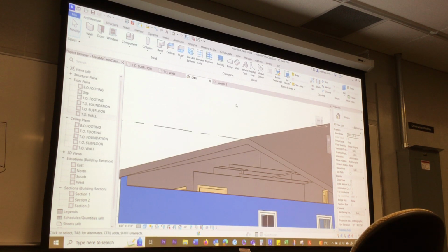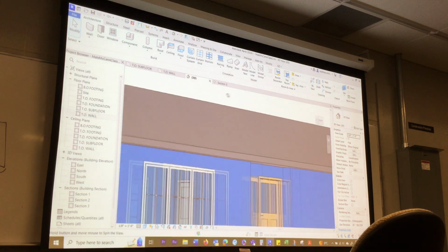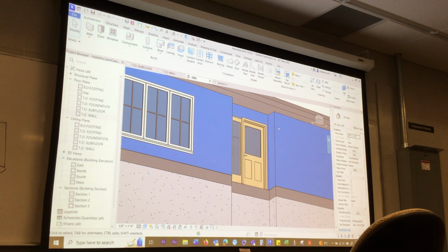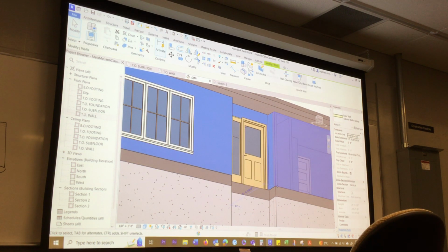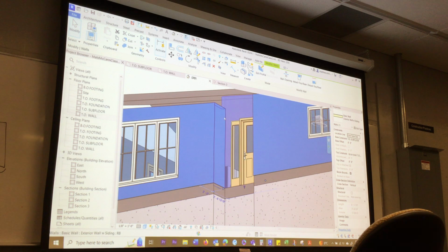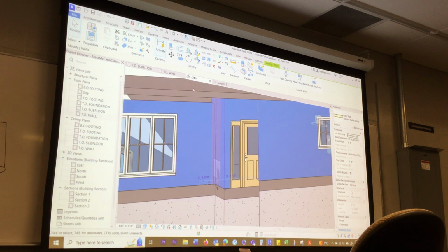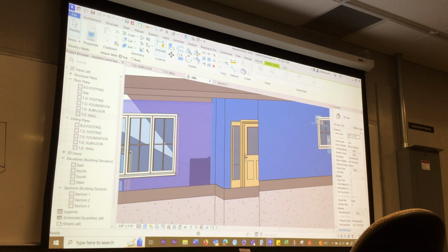We have a problem, which is hard to do, but we'll get to it in a bit. In here it's a bit gnarly, so I gotta be careful. Select that wall. Attach top/base. Select the wall. And you just have to be diligent. I want to get this little guy here. Attach top/base. Select the roof. This guy. You just have to be patient, let it light up. Attach top/base. Select the roof. And I got this little fella in here. It's very satisfying. And then you just keep going around until you're happy.